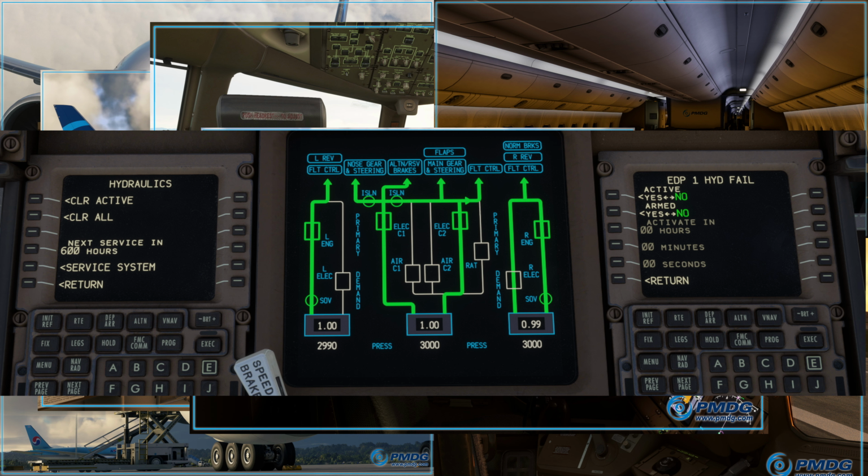Now, every one of the major hydraulic systems in the PMDG 777 can fail. And of course PMDG does model all that stuff really nicely. Now let's go ahead and go into a little bit of the greater details of the hydraulic systems. Amongst others, they included a complete simulation of the hydraulic system with realistic times for pumps to come online and drop offline, and violating the pump operating limitations will cause the fluid to overheat, resulting in an overheat warning.